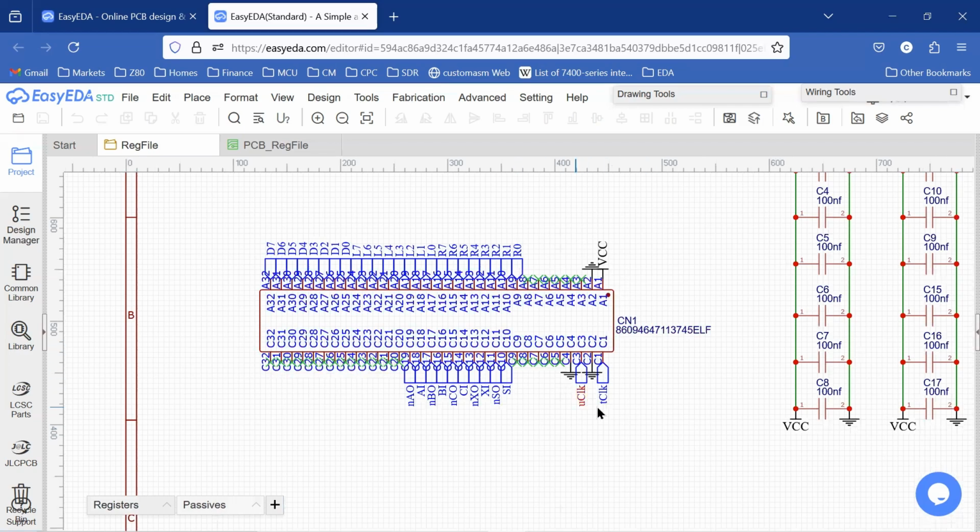So again, these are the standard positions for our clock signals and our clear. It's a clear, P clock, U clock, and T clock. This card only uses the U and the T clock. This will be the area for the rest of our control signals: A in, A out, B in, B out, C in, C out, X in, X out, and stack in and stack out.